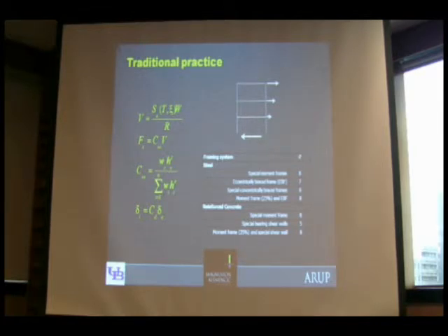If we use this framing system, the 3-story frame, as an example, we go through an exercise of computing a design base shear V. That's the shear at the base of the structure here, and that design base shear is the product of a spectral acceleration, which is a representation of the earthquake shaking, W, the reactive weight of the building, and then this factor R is a response modification factor.